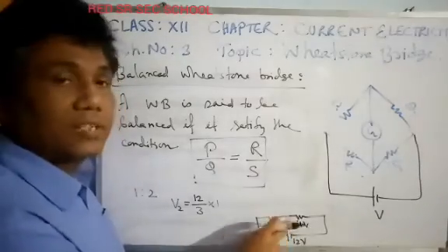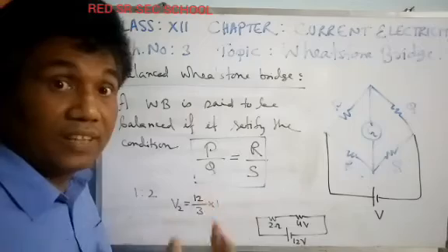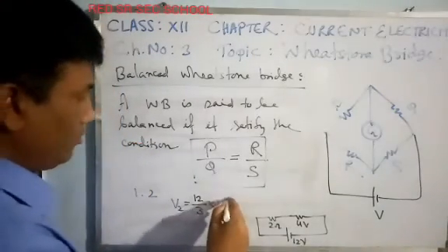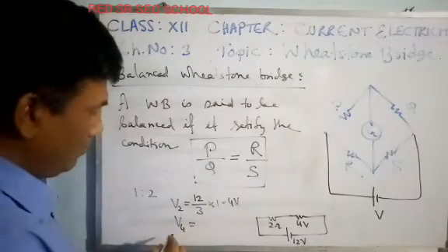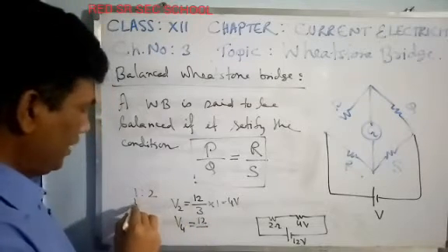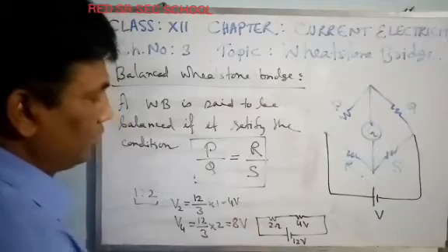Obviously, with more resistance, more energy will be dropped. Resistance means opposition, na? Disturbance. So here the voltage drop is 4 volt. Now what will be the voltage drop at 4 ohm? Total voltage is 12. We have to make 3 parts into 2. It will be 8 volt.